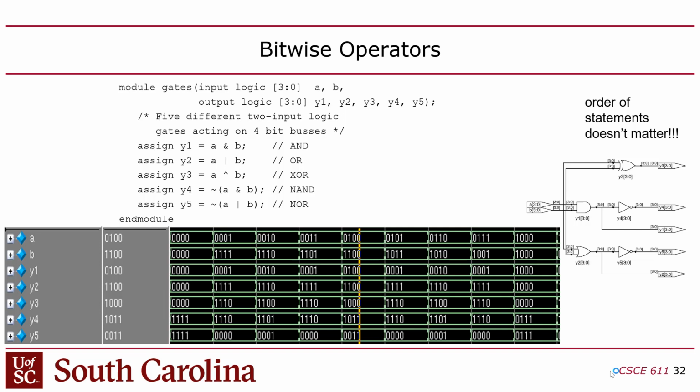But for now, we're just using multi-bit signals. You could think of them as a 1D array, right? Now, the nice thing is that in this case, I've got all these 4-bit values, and I'm using these Boolean operations, and they're treated like bitwise operations in C or Java. So you guys are already familiar with how bitwise operations work. Tilde is a complement, bar is or, ampersand is and, caret is XOR. Those are all traditional bitwise logical operators from other languages. Any questions about that?